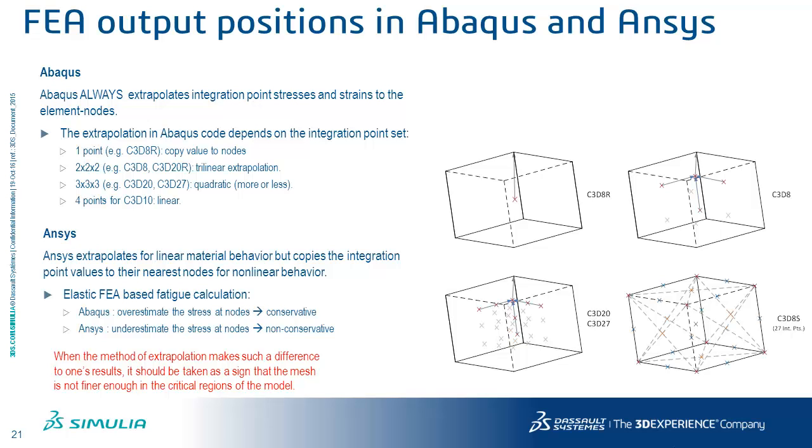And if you use full integration, then as you can see at the top right, we are using trilinear extrapolation, which matches the shape function of the element.